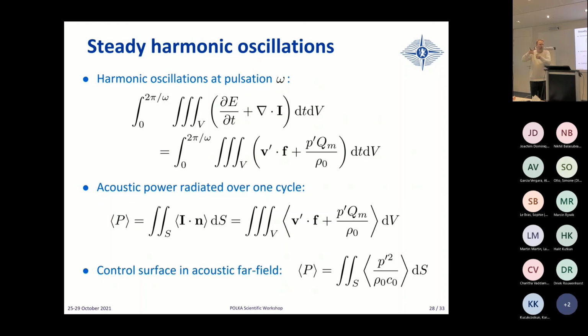If you blow harder on something hot, you extract more heat from the something. And then you have a decrease of heat transfer when the acoustic field is going in opposite direction than the mean advection velocity. Right? So the thing then is to look at, okay, what is the amplitude of my source? And how is it phased with the acoustic pressure field?